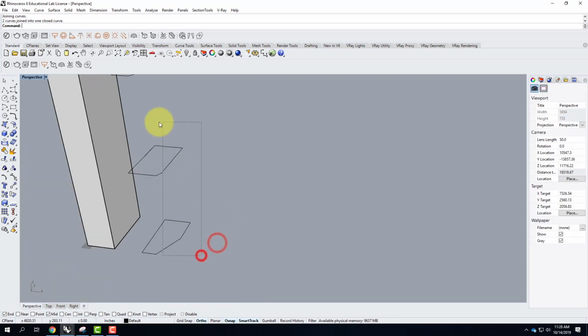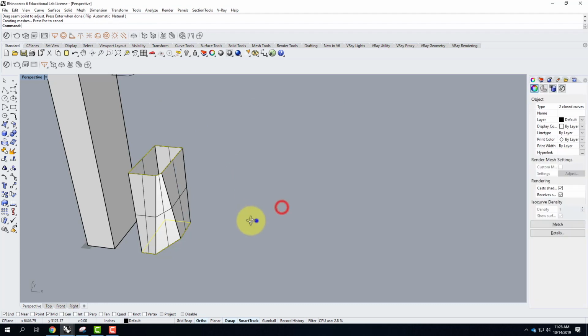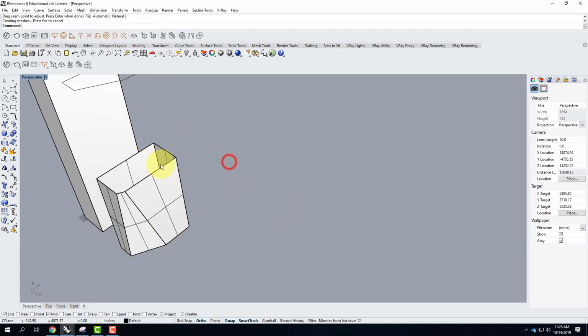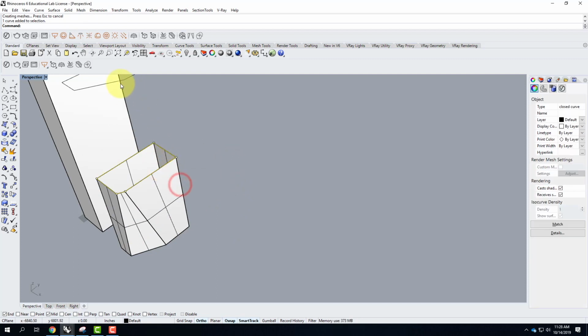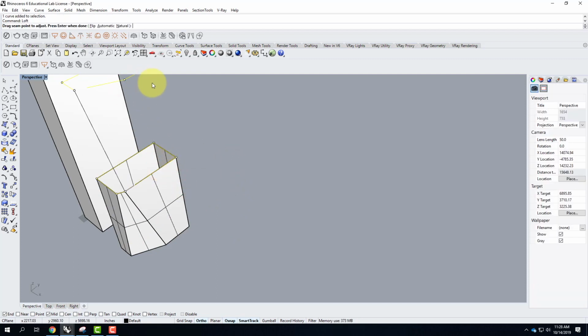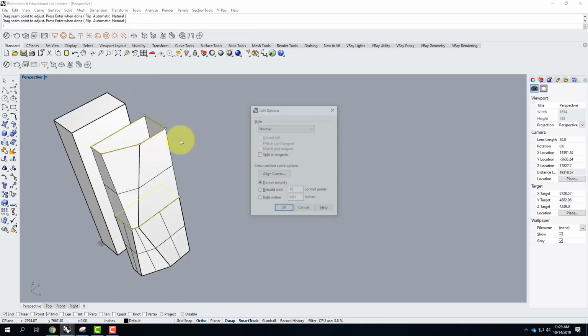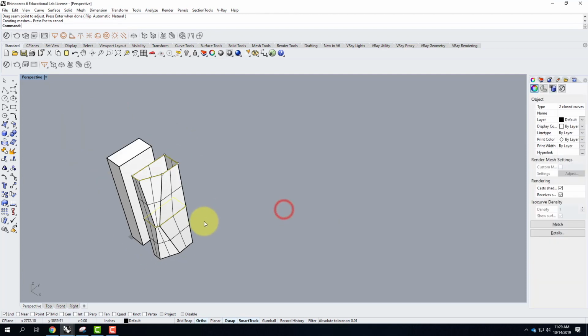And then let me loft these two. That makes it a little bit cleaner, so they're not twisting as much. So I've given myself a little corner there. And then we'll take this piece, and we could loft that together. And again, I want this seam to happen there. And so maybe it looks like that.